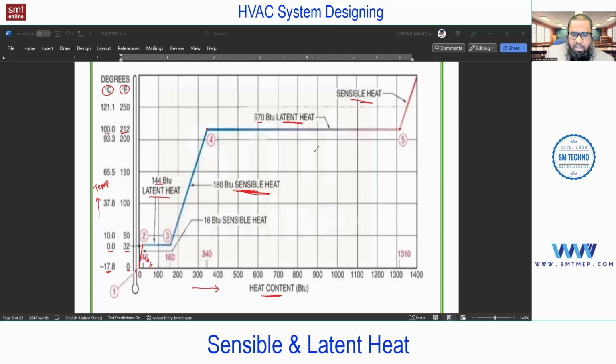Because without that, you cannot think about this classification of air conditioning. Even in chilled water systems, in chillers, you'll find a vapor compression cycle. You also have vapor absorption chillers. Commonly in actual practice, compared to vapor absorption, the compact type is the vapor compression cycle chiller. We have a detailed topic. So at this level, just focus on this topic so that we can use it at the time of the vapor compression cycle. Okay. So did you get the idea about sensible and latent heat?